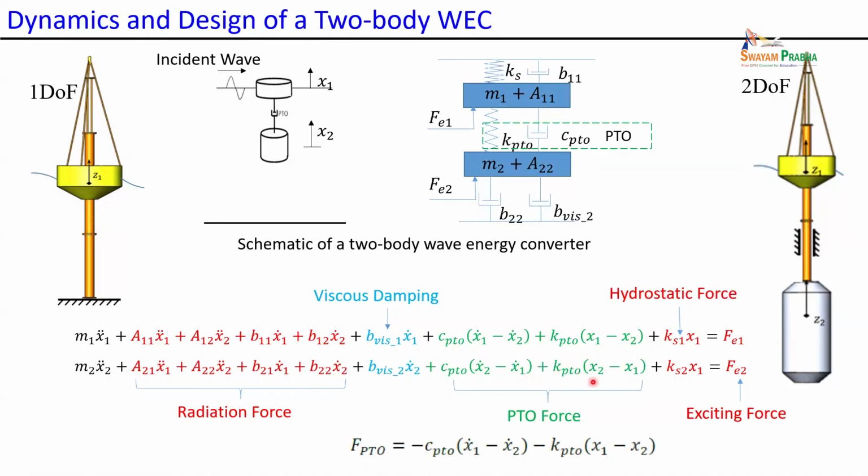Okay. Now this is a 2-degree freedom vibration system. Now you can solve the 2-degree freedom vibration system. Now the design, what's the design freedom? Similar to what we learned just now, how to choose the PTO damping, how to choose the PTO stiffness, right? How to choose the PTO inerter, right? So most likely when we say suboptimal, we can set PTO K to be 0, right? And so then you can solve for the optimal damping.